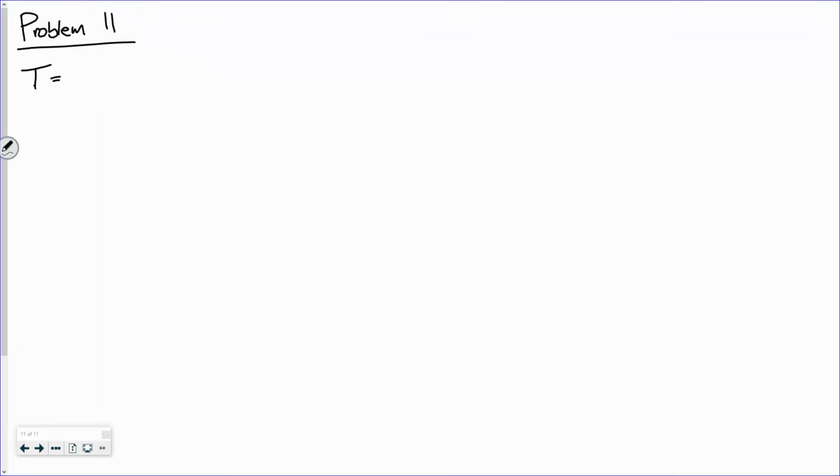We have a torque applied that's 100,000 Newton meters, okay? Now, the length is 3 meters, okay? Where we're going with this is as follows. Ultimately, we're trying to determine the angle of twist, which for a shaft loaded in torsion is TL over GJ.